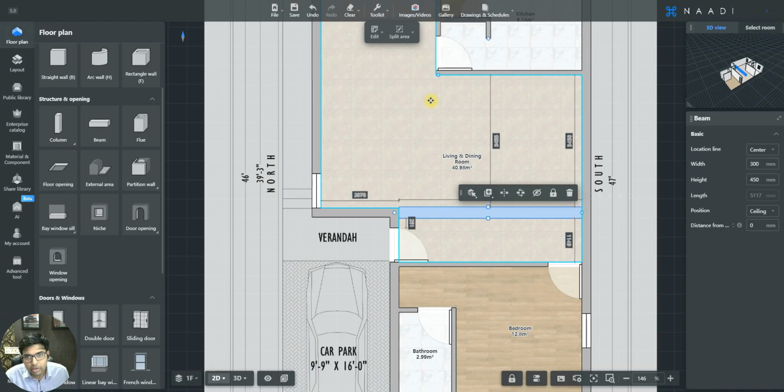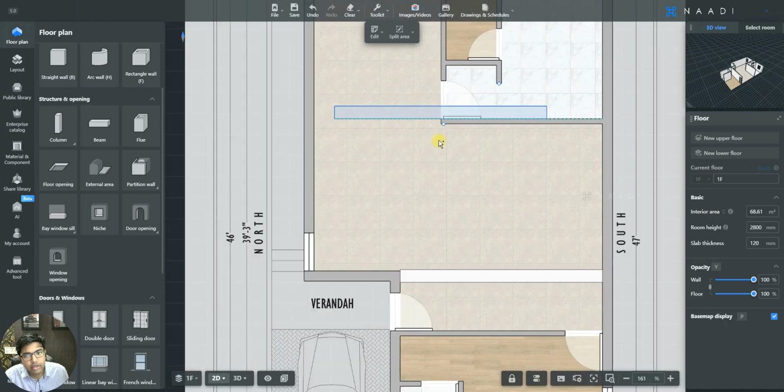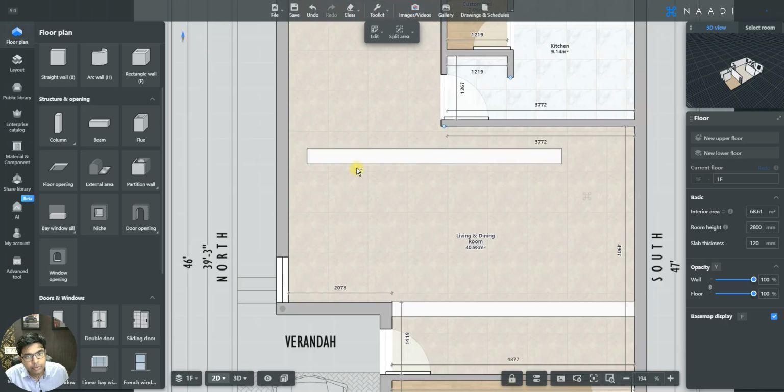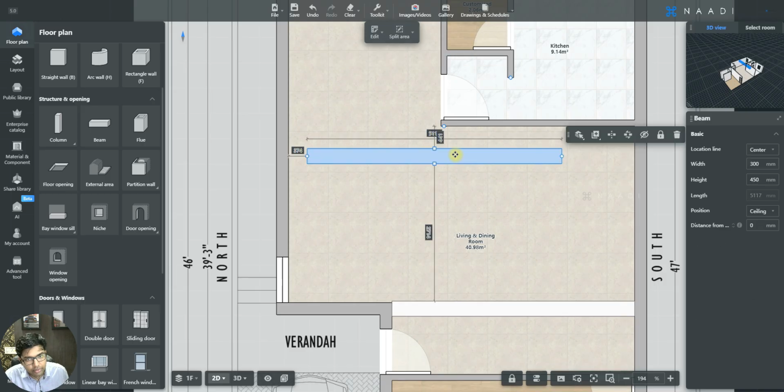And now if you want another beam which has the same specification, you don't have to again take it here and do this process. Just select the beam which you created, press Ctrl C, and now we can precisely position it at different points here. Don't worry about the direction. Once it is placed, you can click that component. It will show you respective toggles here.